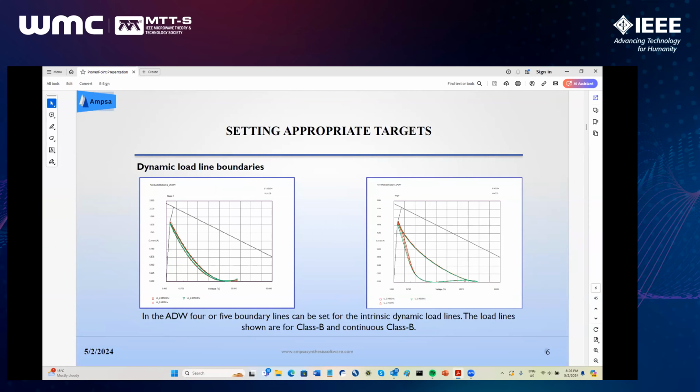And you make these boundary lines basically follow those IV curve boundaries. So that defines a knee for you, and the knee could be sloped. So usually it would turn around here somewhere, and then the maximum current boundary, you have a breakdown boundary somewhere, and minimum current boundary for class A or whatever. Now the good news is this applies to all the classes. So this environment can do class A, B, C, not C, all linear classes, B, F, inverse F, and also a thing I call B2, but we can talk a little bit later about B2 if we have time.